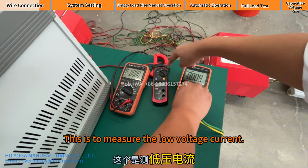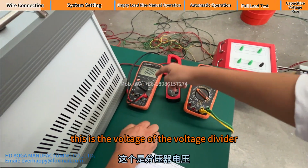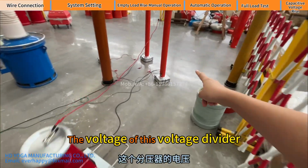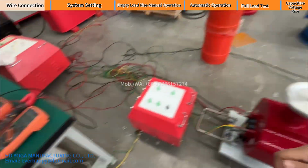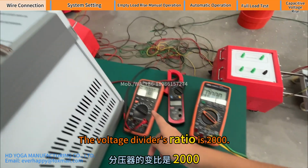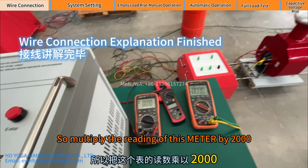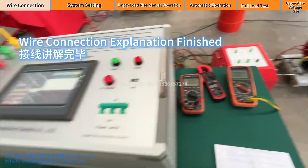This is to measure the low voltage current. This is the voltage of the voltage divider. The one I point to, the voltage of this voltage divider. The voltage divider's ratio is 2000, so multiply the reading of this meter by 2000. That's the voltage of the voltage divider.